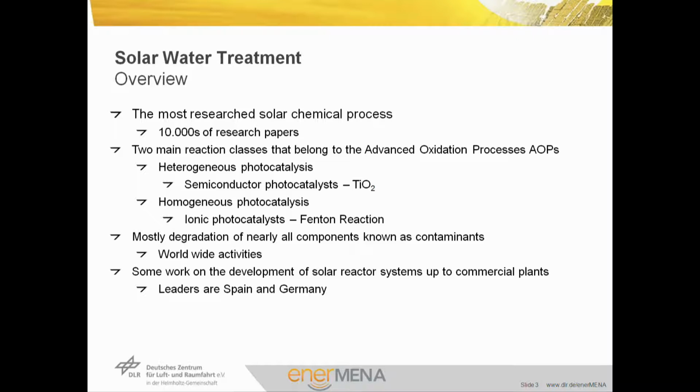There are 10,000 of research papers on water treatment processes published already, and there are two main classes of reactions that are under research, and both belong to the so-called advanced oxidation processes, or AOPs. These are heterogeneous photocatalysis, where we use semiconductors as catalysts, like titanium dioxide, and homogeneous photocatalysis, where you use dissolved ionic photocatalysts, like the Fenton reaction. Most degradation of nearly all components known as contaminants are carried out. There are worldwide activities on these, and worldwide excellent work is carried out.